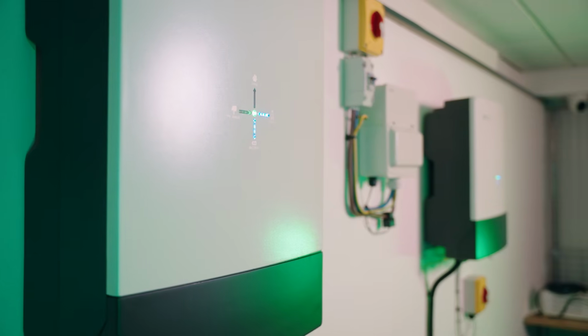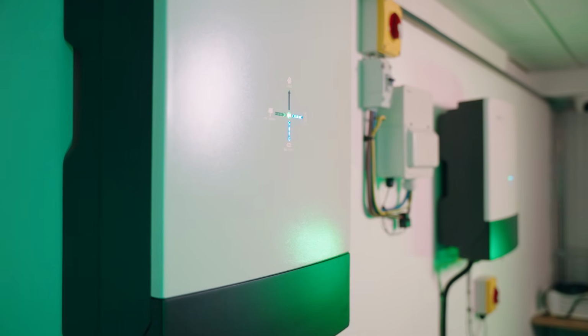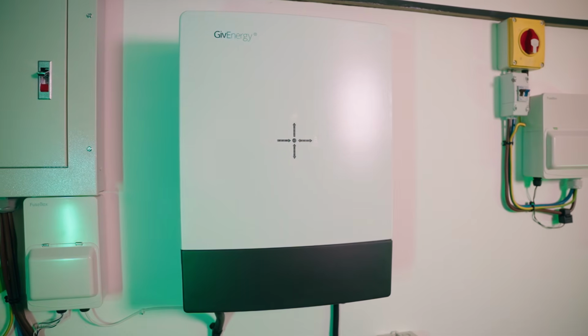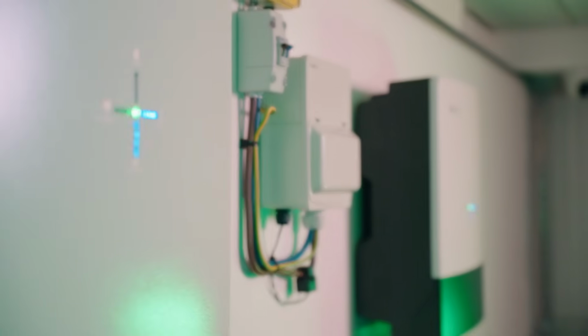Then you would pick your inverter that would be appropriately sized to the solar panels. If an inverter is too big and your solar system is too small, then you can have a risk of it not firing up or not firing up regularly enough. The other aspect to it is you have lots of solar panels but your inverter is too small, your inverter can throttle the amount of energy and essentially you lose out on your valuable return on your investment.